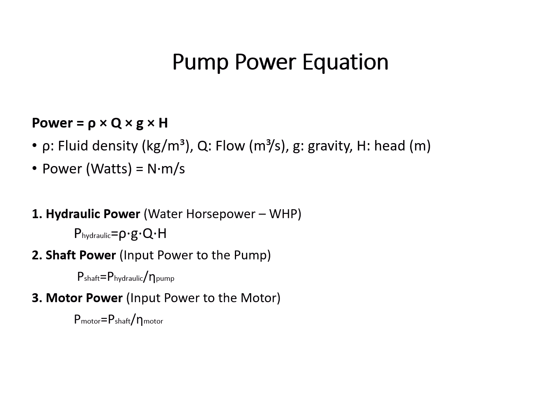The shaft power, the input power to the pump. This is the power supplied to the pump shaft, and this power will account for the pump efficiency. It shows you how much power is delivered to the shaft, and how much the pump is able to convert the input power, which is the electricity, into shaft power.